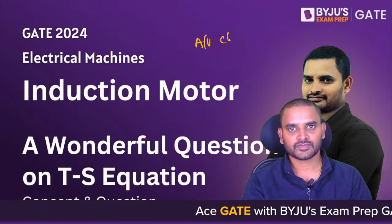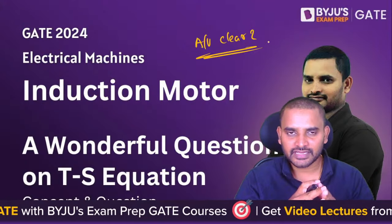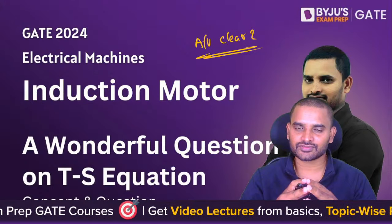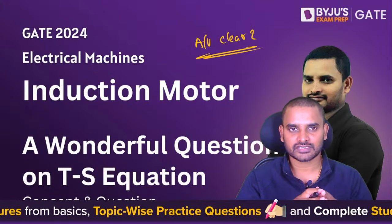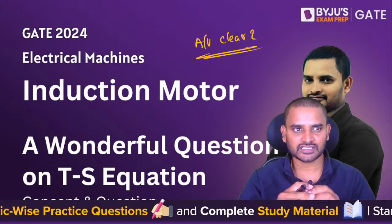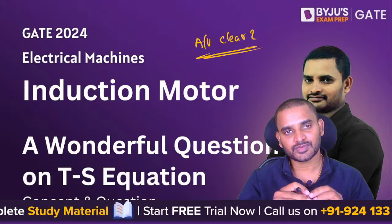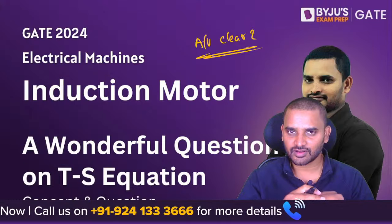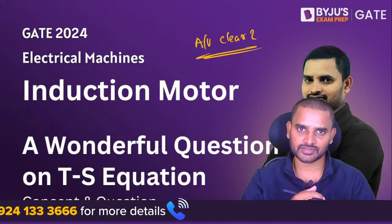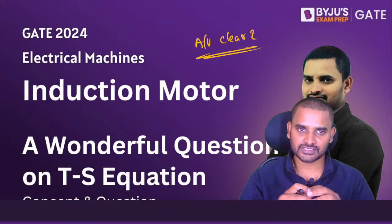That's good. So, in the last session, I tried to explain one very good question on transformer efficiency and losses. He has given some information at 50 hertz rated voltage, and some other information at rated voltage and 35 hertz. So, if the frequency of operation changes, how the iron losses are going to change, we did, and from that we calculated the efficiency also.